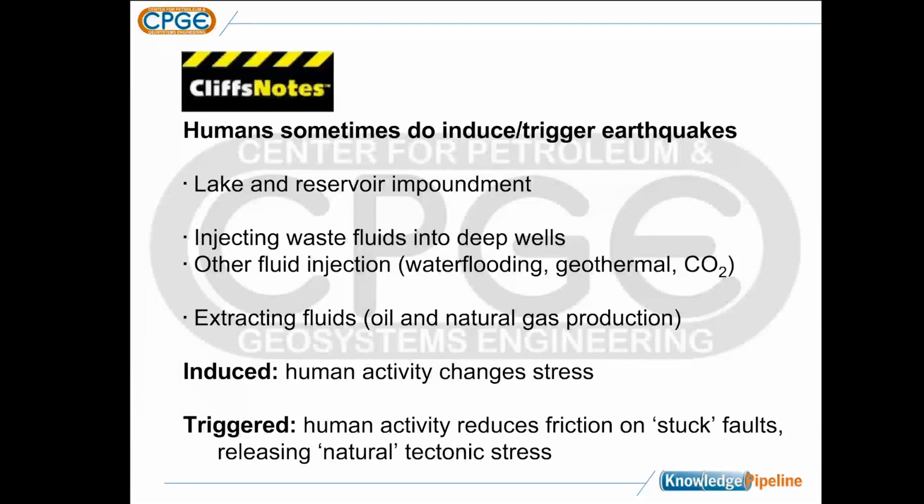And sometimes people make the distinction between induced and triggered earthquakes. When they make this distinction, an induced earthquake is where the human activity actually changes the underground stress. For example, when you fill a lake, the weight of the water increases the stress on a fault beneath it, and so that could induce an earthquake.